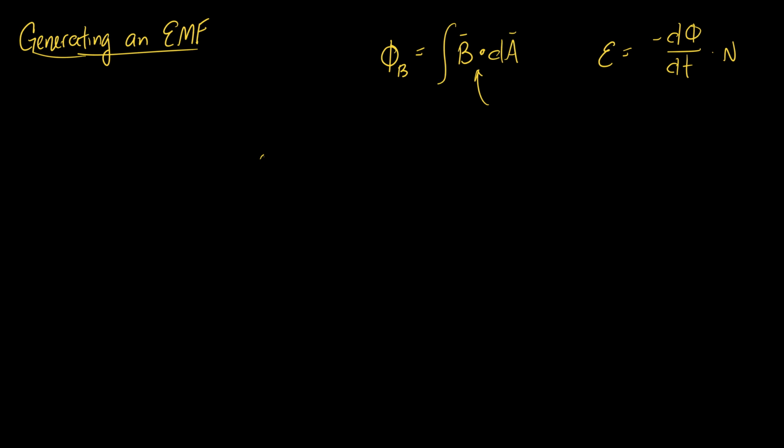By the way, this is probably one of the primary ways that we actually generate electricity. There's two different ways. There's rotating the magnet inside the loops, and there's rotating the loops inside a magnetic field. We do it one way or the other, but every turbine generator is operating on that principle. Something's rotating, something's spinning, either because you're passing steam through it. If you're burning fossil fuels and boiling water, you're putting it on the top of a pole and letting the wind blow it. You're using some kind of steam brought up from a hydroelectric plant, or you're allowing water from a dam to flow over it.